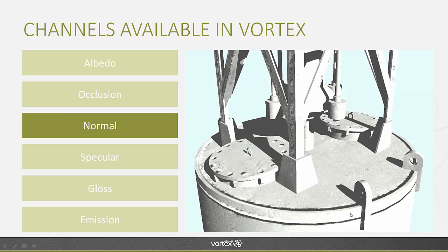So if you look here, we have a seam, a ridge on our cylinder that, as you remember, is not there. The normal map will affect the way light is reflected, in which direction it goes, and if light is reflected at all by a specific portion of the model, to provide a visual impression of volume that is not there. So this is still a perfectly smooth surface, but because we've added a normal map, it looks uneven.